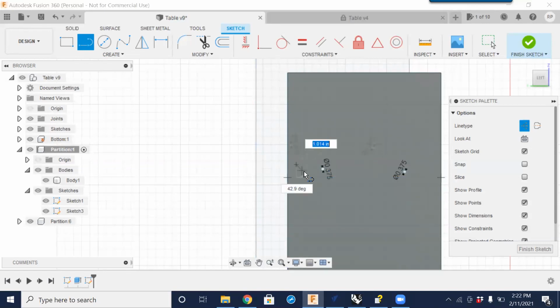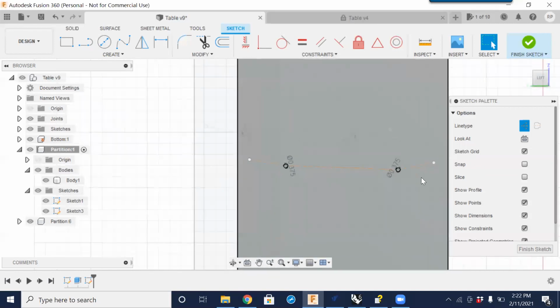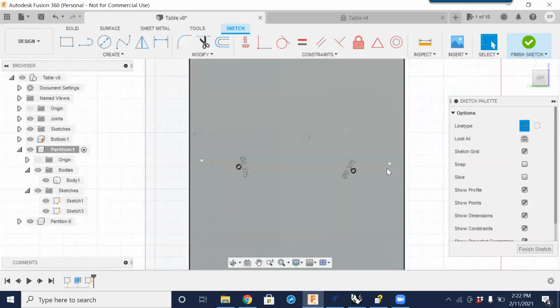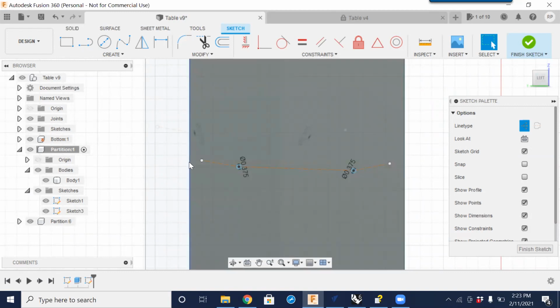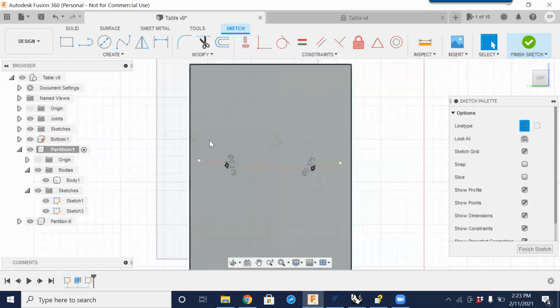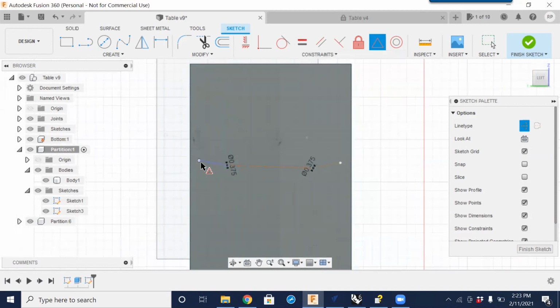And what this means now is I'm able to snap a line. And I'm purposely drawing those off of an angle just so we could see what constraints are and what they do. So we have this endpoint and this endpoint here that I always want to be to the same edge of our part, or maybe even to the center of that part, the midpoint. So I'm going to use the midpoint constraint, selecting that end dot and then selecting the line. So that just automatically snapped and positioned this line to be the midpoint of our line span.